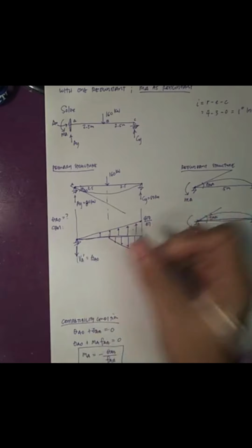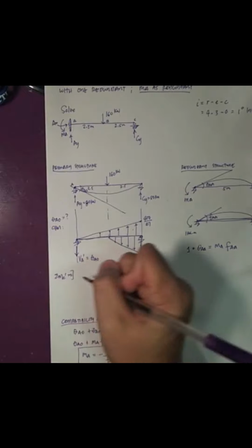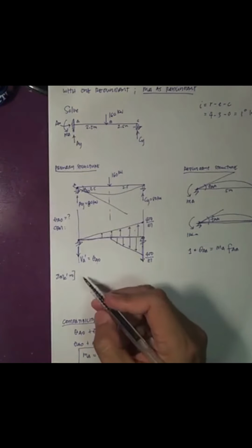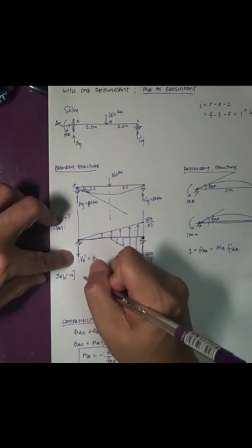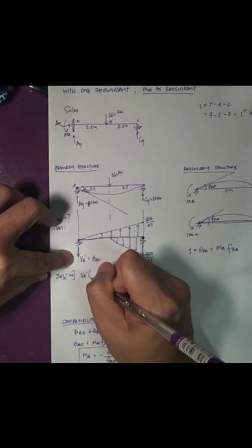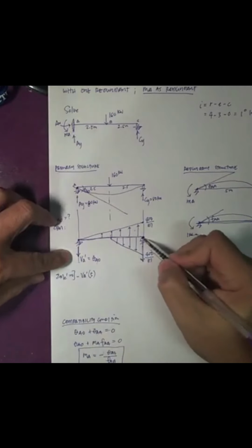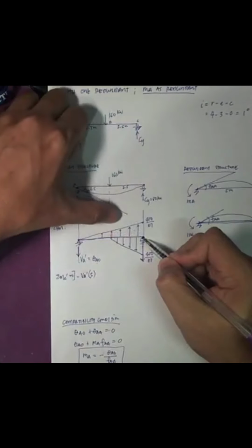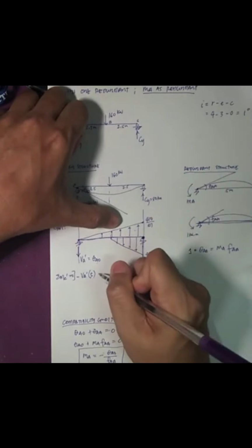So how do I solve for this? So I'll take moment here. So say summation of moment at say C prime equal to 0. Let's say clockwise is positive, counterclockwise is negative. So what are the moments? So I'll have BA. So we have BA times 5, and that is counterclockwise, so negative. Okay. Then the triangular load on top, that would be clockwise, so plus.